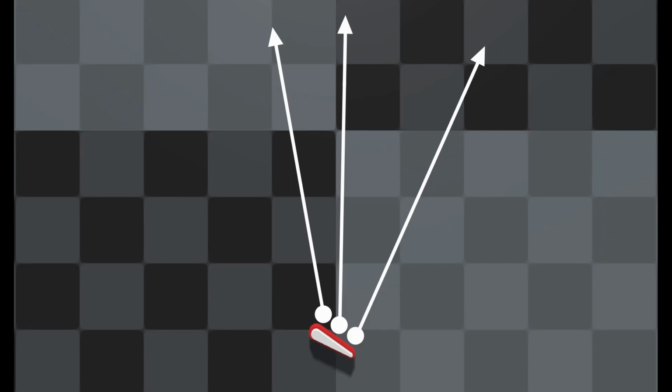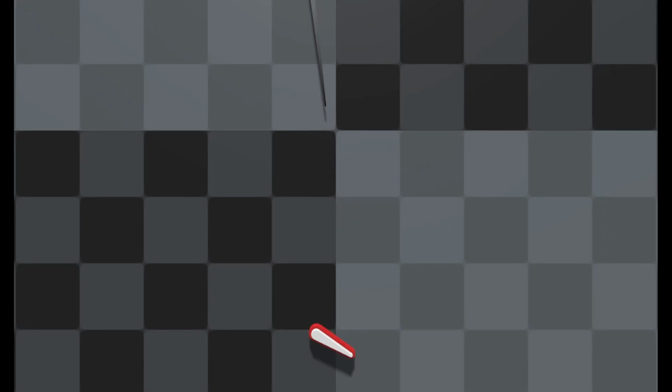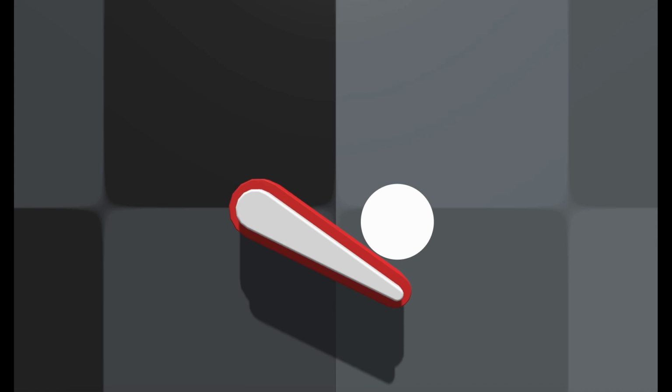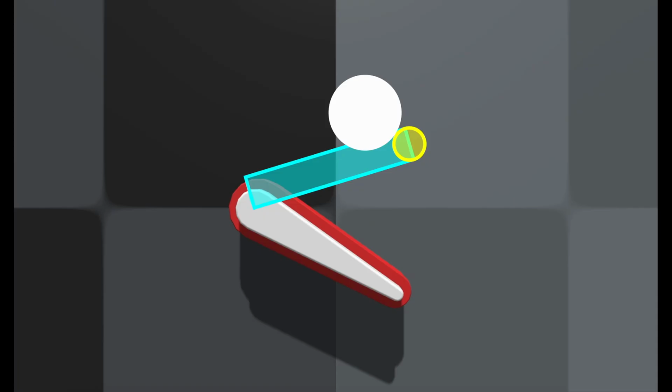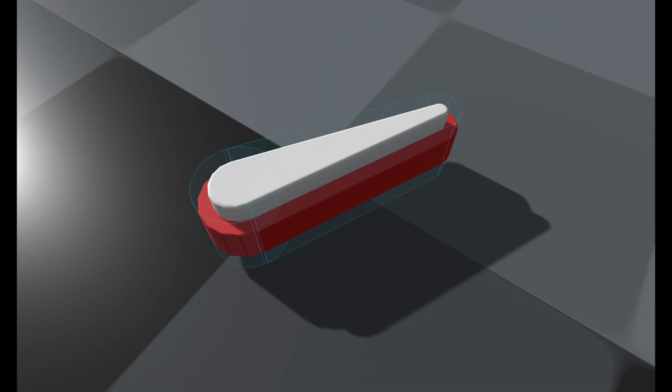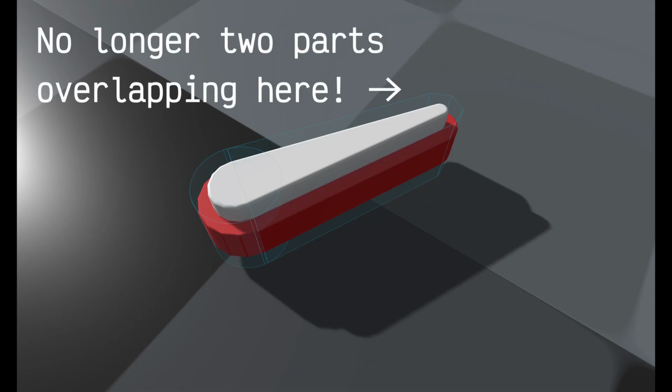But for some reason, when the ball is placed just right between the center and the tip, it gets launched as if it was near the base, leftwards. I have a theory where the ball is processing collisions separately from the box and cylinder at the tip, and when it comes to calculating the cylinder collision as it flips, it pulls it back because of the angled surface of the cylinder at the tip, instead of prioritizing the closer, flatter surface. So for the middle and the tip, I will use a convex hull shape. I get better results for that area.